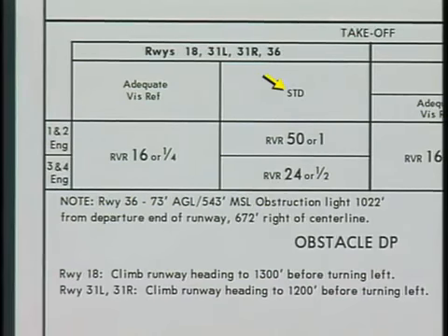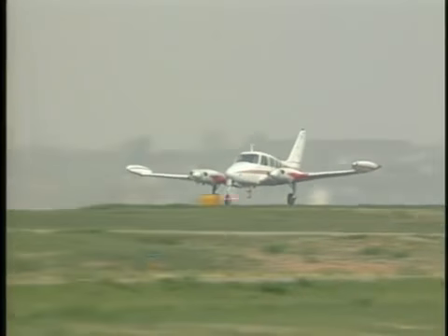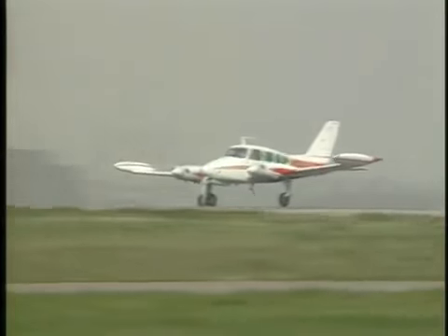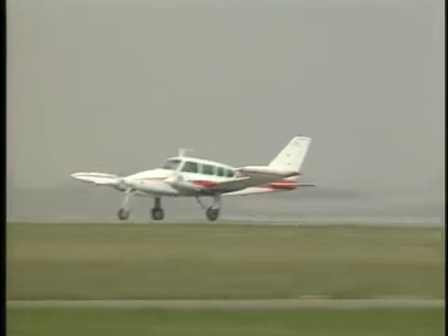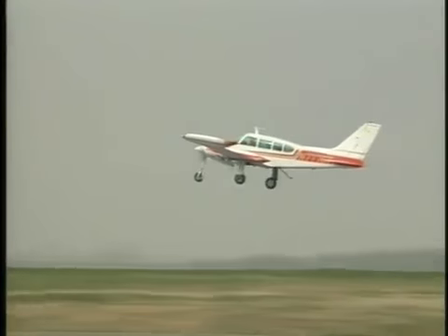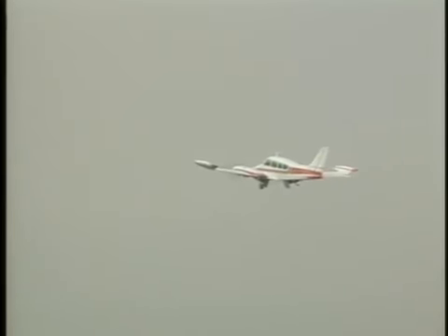For example, the STD column under each grouping reflects the standard takeoff minimums prescribed in the FARs for aircraft with 1 or 2 engines or for aircraft with more than 2 engines. Remember, if you're operating under Part 91, you are not required to comply with the published IFR takeoff minimums. However, you should realize these minimums have been established for the operation of commercial aircraft. Therefore, it is wise to comply with the standard minimums.